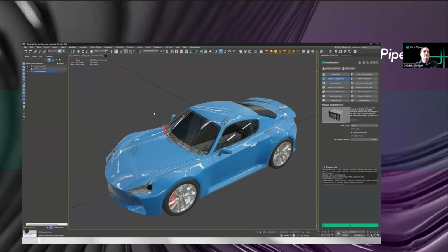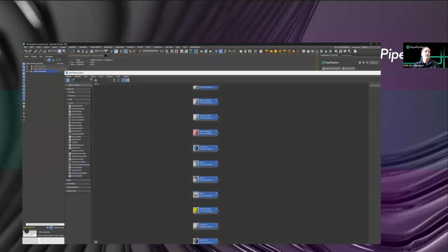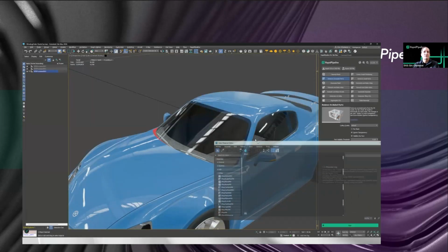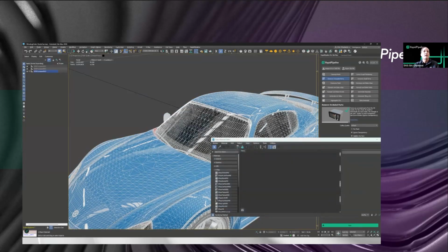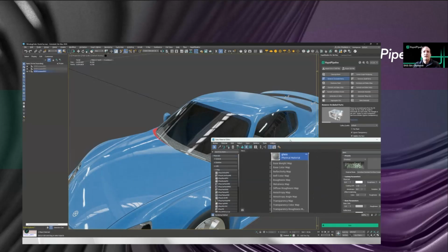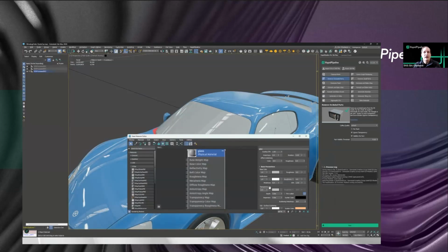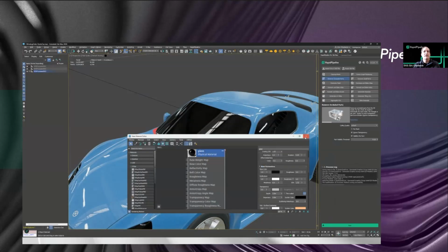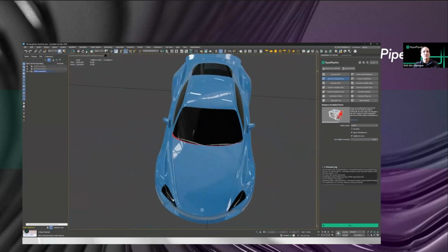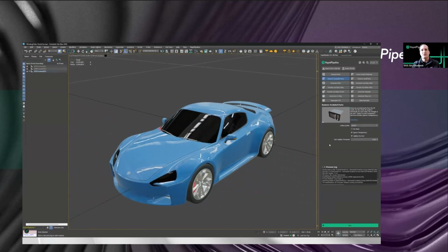So now we've gotten down to 2 million, which is great. And maybe we set this material. Let's go to the material editor here and grab the material from that guy, get from selected, and there's our glass. So maybe in this particular example, I'm not going to have transparency. I'll turn it off and it's going to be tinted glass. And then it works great. I never see those surfaces in there. Why keep them around? And that's occlusion culling and how it works.